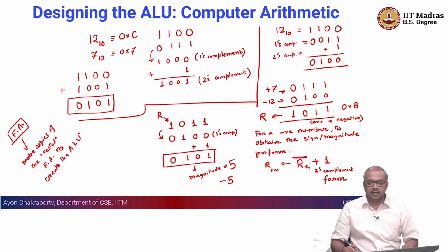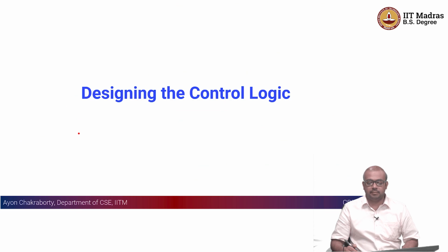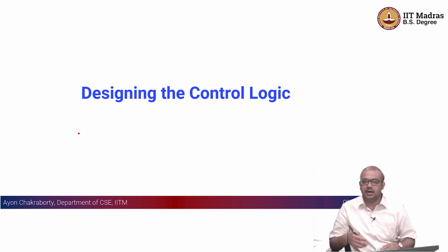Okay. So, I think in the last class I have mentioned the different components being the register file, then we spoke about the ALU, then I have to talk about the control logic, and this is primarily the brain of your CPU, which orchestrates all the data transfer and operations across the components, right. This is primarily going to control which one of the components are supposed to do what at a certain point in time. And as I told you, every instruction